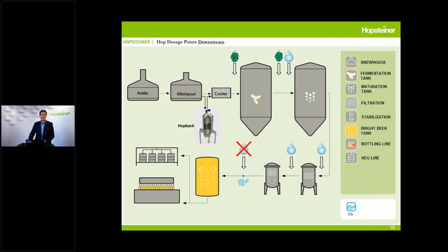So now we come to the downstream area, to the cold block, where some people add hops for fermentation, some people add hops to maturation or to the end of the maturation. That is what we call dry hopping. And also here's the point where we can use hop oils for the first time, where it makes sense. Instead of pellets, instead of other hop products, we can go to hop oils, partial or completely, and then we transfer the hop aroma compounds from the oil into the beer.